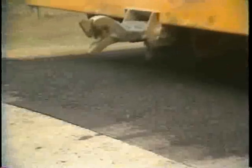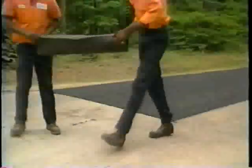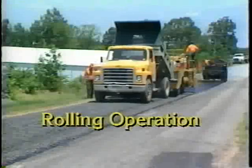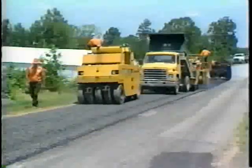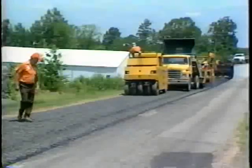The aggregate spreader also begins and ends spreading aggregate on the building paper, just as the asphalt distributor. Once the aggregate is spread, the paper is removed, leaving a straight and neat joint. Following the aggregate spreader, step number 6 is the rolling operation. The rolling operation proceeds immediately behind the aggregate spreader.